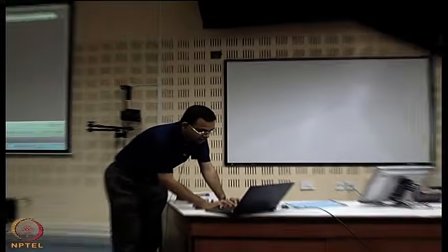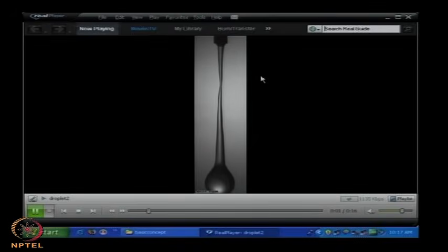So, we look into the second example. Some of the examples later on may appear to be even better than what you saw earlier. So, this is breaking up or kind of necking of a liquid column. There is a liquid column, it is getting broken up, and the reason is that, see, what are the forces which are acting here? One is viscous force, another is surface tension force, we will come across that, and there is a competition between these two. So, if the viscous resistance is overcome, maybe surface tension driven instabilities can break it up or tear it up into nice pieces.